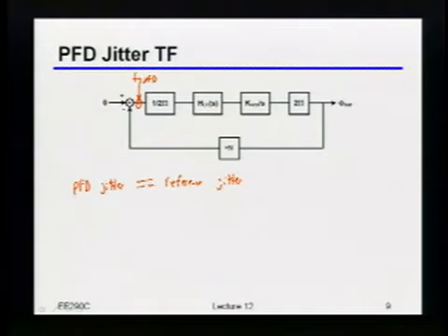Okay, so if we figured that out, then now we can make our life more fun. We can move to the next component. So let's assume that you've built a charge pump PLL, and let's see what the impact of charge pump noise will actually be. I'm just going to redraw my overall loop model here. And by the way, I should point out, I'm now being more careful about the factors of 2 pi because I'm going to be starting to insert noise in places where that factor actually matters. Okay, so I've got my 1/2 pi from the phase detector.